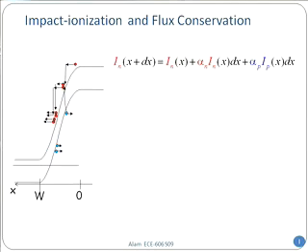And the same thing is going to happen for the holes, because for the holes, the world is upside down. Holes would like to go from left to right, and this electric field assists them. When in a high electric field a hole has enough energy, it can scatter and generate among themselves, and it can also pump an electron up to the conduction band. So this avalanche goes both ways, in parallel.